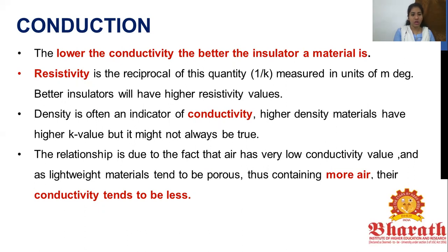Talking about how, though liquid materials are denser, they don't have as much conductivity. So you could not define that denser materials are good conductors. There are a few exceptions in such cases. The relationship is due to the fact that air has a low conductivity value, and lightweight materials tend to be porous, thus containing more air, so their conductivity tends to be less.